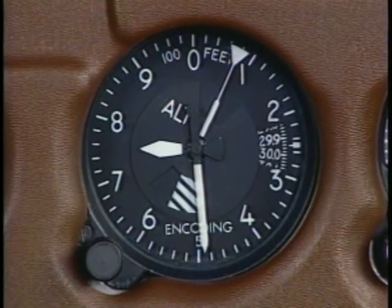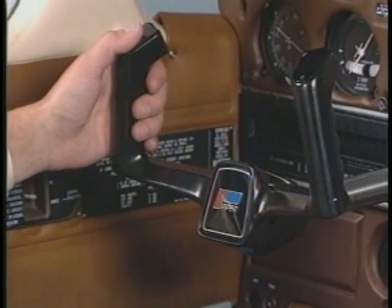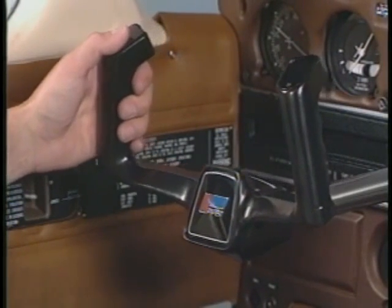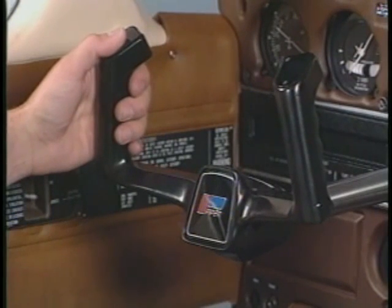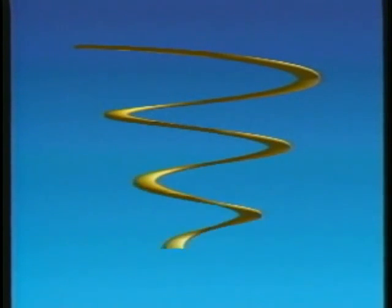Another situation occurs when you begin losing altitude. If you attempt to climb back to your altitude by pulling back on the control wheel, you only tighten the turn and increase the load factor. The result is a tight descending spiral, an accelerated stall, or possibly structural damage.